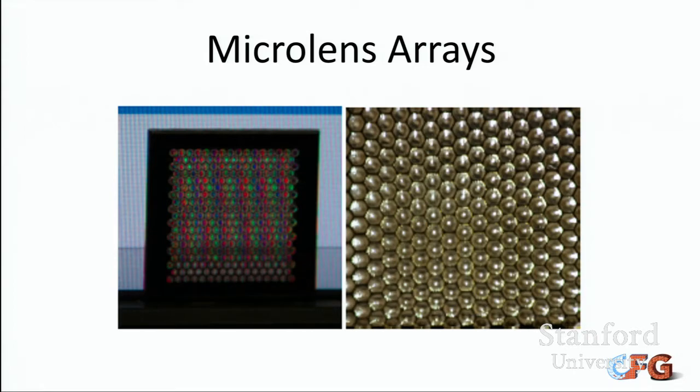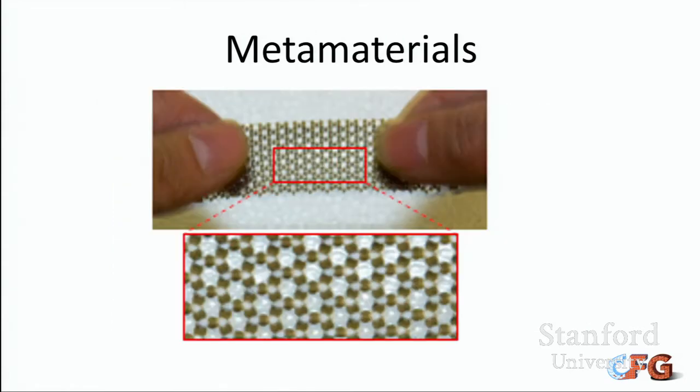So what can we do with this type of system? Well, for example, we can print different optical components. We can print microlens arrays for example, with specially applied baffle. We can even print on the top of the surfaces or screens directly with correct alignment. We can print different metamaterial structures, for example, combining different elastic and rigid materials, and for example, in this case, building a material that has negative Poisson ratio. Basically, if you are trying to stretch it, the material is going to expand.